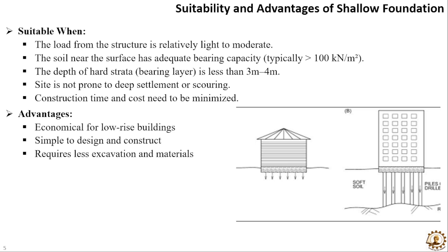Now, while we can use these in map out questions, you may have seen the question: in which situation should we consider a shallow foundation, or in which situation should we consider a deep foundation? Shallow foundation we will consider when the structure is relatively light to moderate. So the comparison is like that.